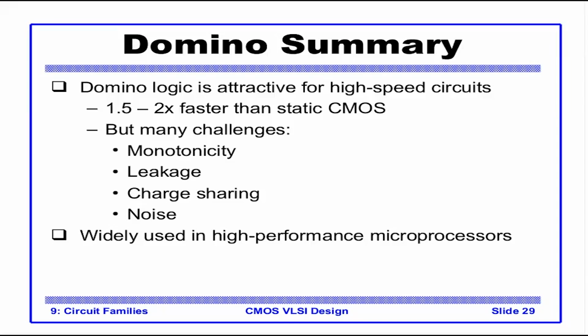It might be slow, it might be big in area, but it is very robust, and that counts. One more thing is that in domino we have the clock input. Routing the clock to thousands or millions of transistors, having an extra input like clock which goes to everything, is not easy. The routing resources would be huge, and so the transistor count will not increase, but the wire area, the interconnect area, will increase. So having an extra input as clock is not an advantage.